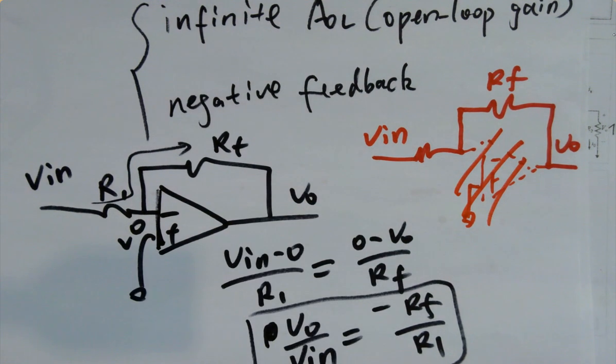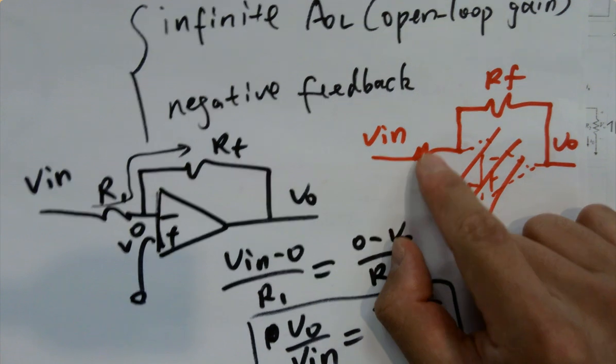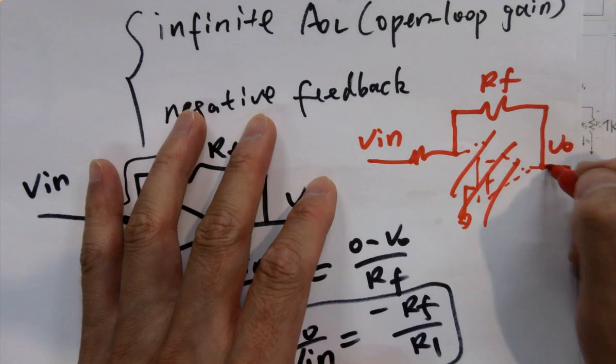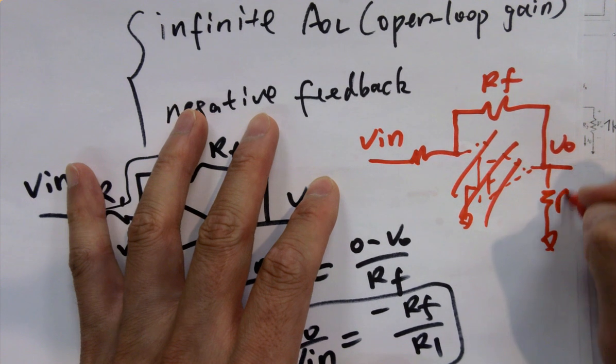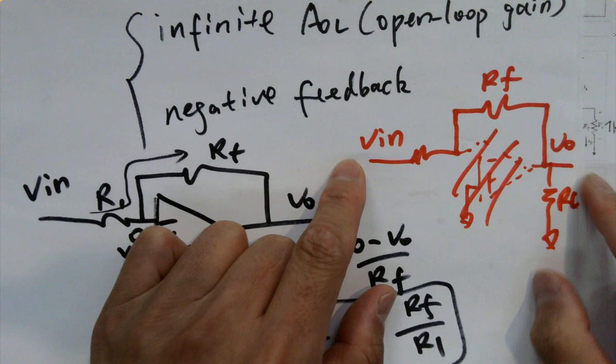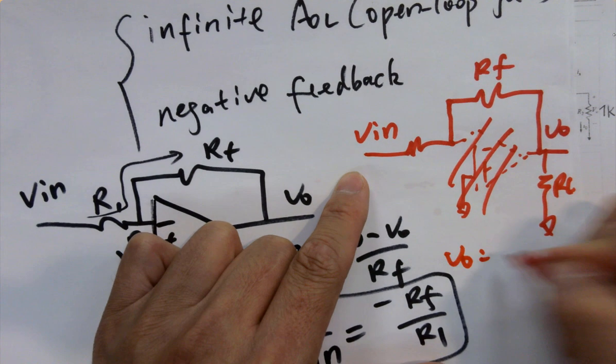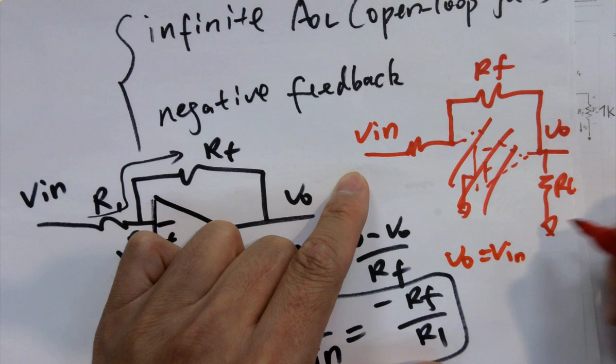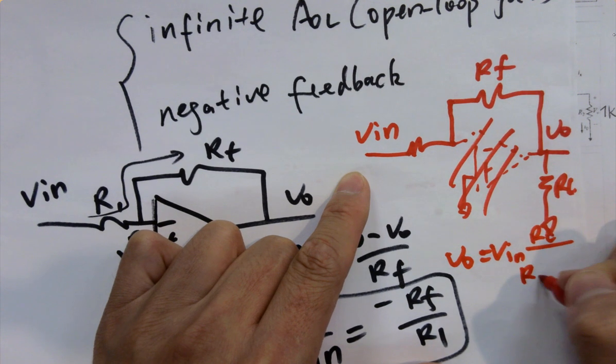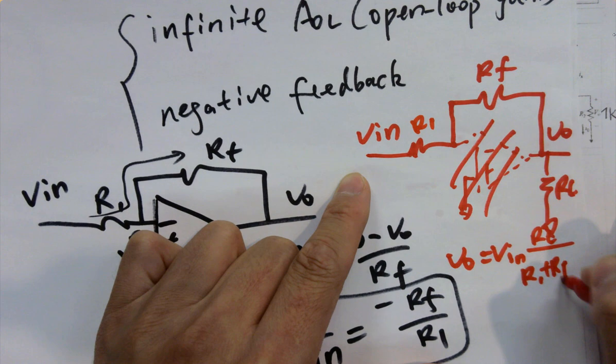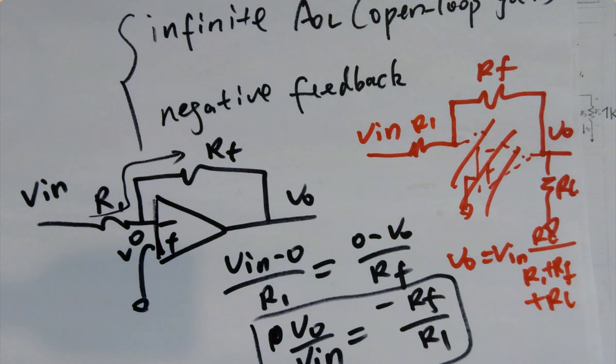What's gonna happen? Are you amplifying anything? Why? You just run into two resistors. It's dropping by 2 times, depending on what these are. If you have a load resistor, what's happening? It's a voltage divider. V out is what? V in times what? RL over what? R1 plus RL. Are you amplifying anything? Are you able to amplify it? No, it's a voltage divider. It's dividing the voltage.